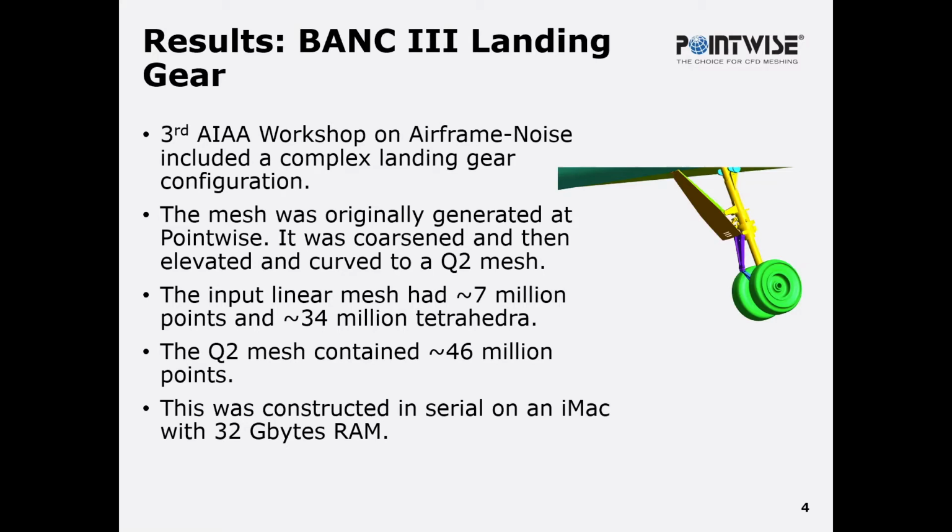The input linear mesh had 7 million points or nodes and consisted of 34 million tetrahedra. And the quadratic mesh contained 46 million nodes. But this was constructed on quite a small machine, really, just in serial on an iMac with 32 gigabytes of RAM. So something that you can just buy from a department store. It's not really a high-spec computer.